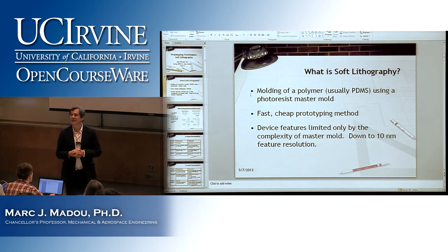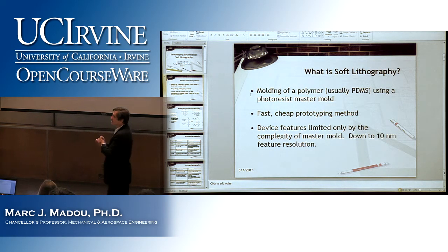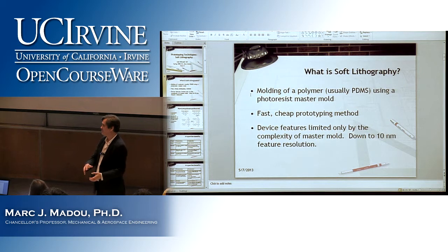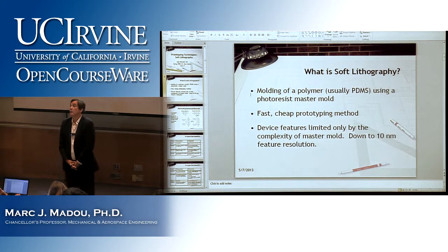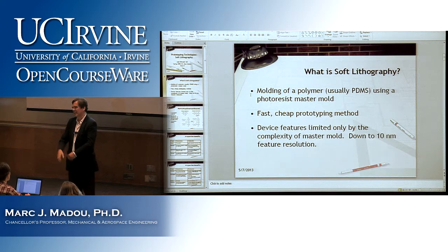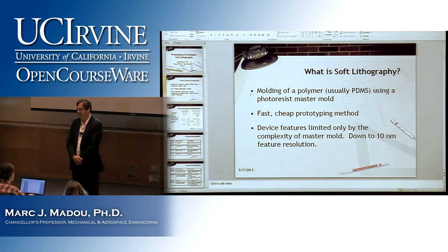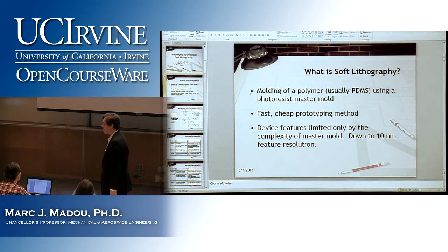Now, can anyone imagine there is actually a technique out there that's kind of a family to soft lithography and made it possible to really put it in manufacturing? Does anyone know? So what you would think about it, logically, to make this into a real manufacturing technique, I kind of already suggested what you would have to do. Instead of having a floppy material, you make it more rigid. And so that is exactly what people have been doing. They have nano-imprint lithography, NIL, a very, very important technique, even being promoted as perhaps one of the next lithography techniques.